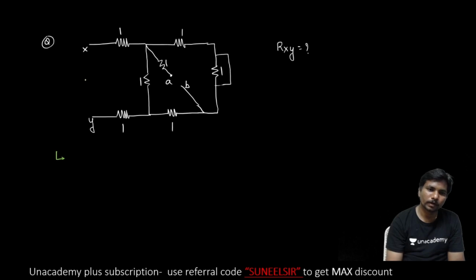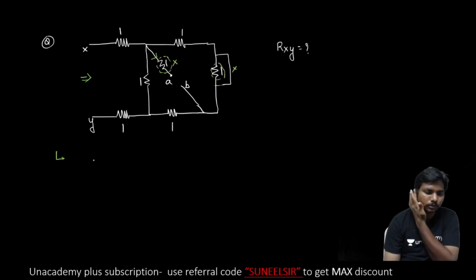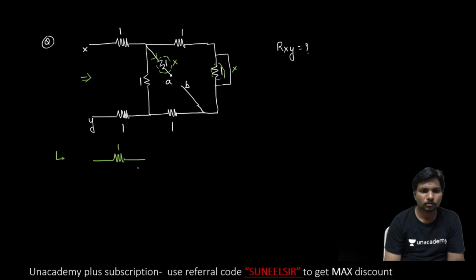If you are going to find RXY, there is no current flowing through this 1 ohm resistor, so it can be eliminated. And this resistor is parallel to the short circuit, so it is also eliminated. Then what is your circuit? 1, here 1, here also 1, here 1, here 1, and the one parallel to the short circuit is eliminated. So we can write it like this.